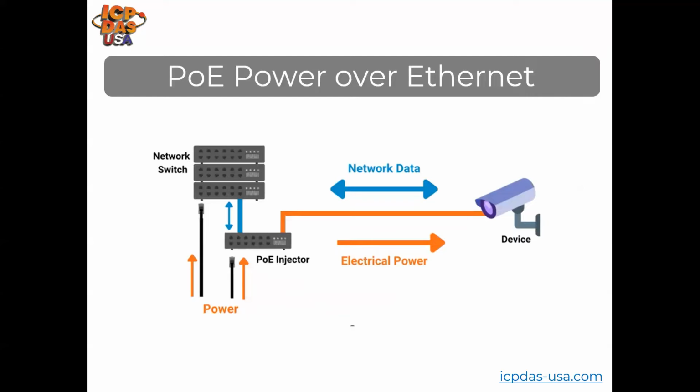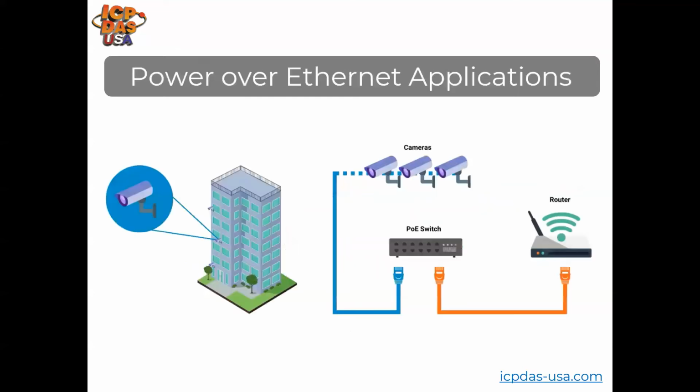Power over Ethernet allows for transmission of power and data through the same cable. It's often used in areas where electrical outlets are not available to provide power. Some devices that are commonly powered over Ethernet are IP cameras, access control devices, voice over IP phones, and serial device servers. One way power is provided over Ethernet cabling is a power over Ethernet switch. An Ethernet cable is attached to the powered device, can be run up to 100 meters, and you can provide power to the IP camera.